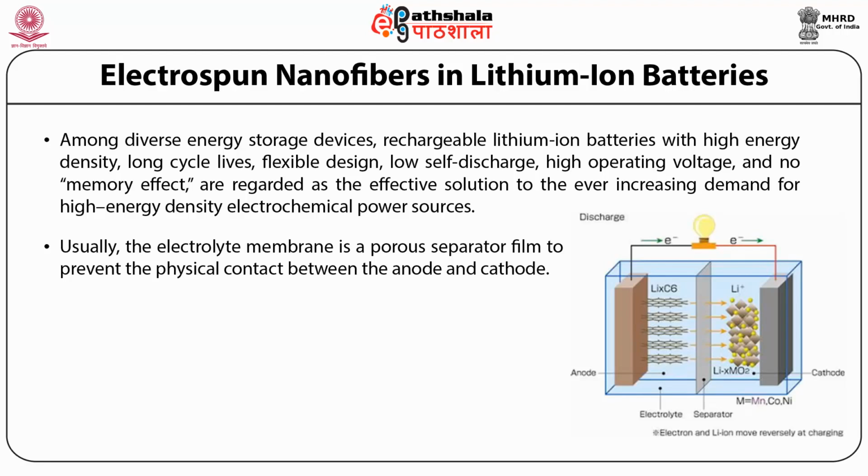As the battery is being charged, an external electrical power source injects electrons into the anode. Simultaneously, the cathode gives up some of its lithium ions, which move through the electrolyte to the anode and remain there. Thus, the electricity is stored in the battery in the form of chemical energy. As the battery is discharging, the lithium ions move back across the electrolyte to the cathode, releasing the electrons to the outer circuit for external electric work.